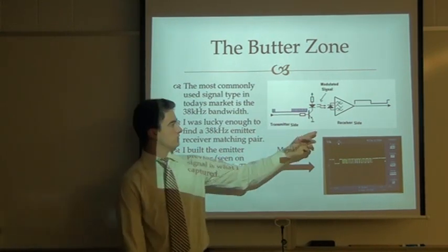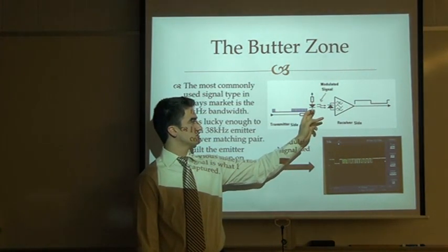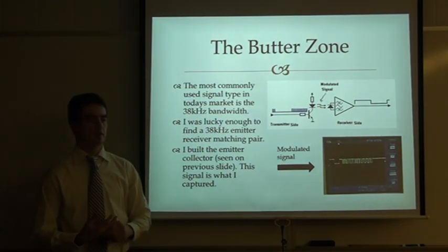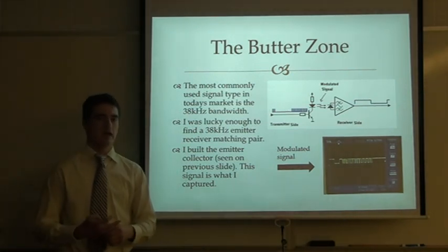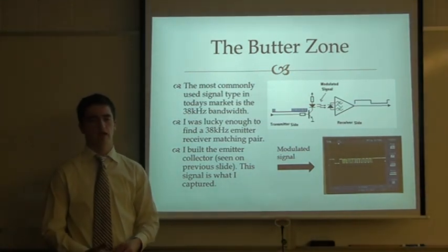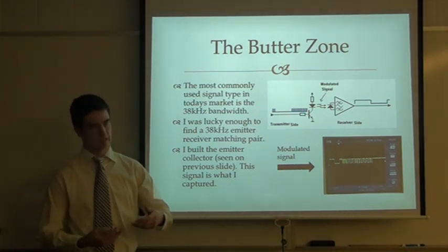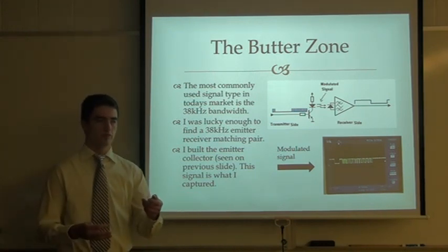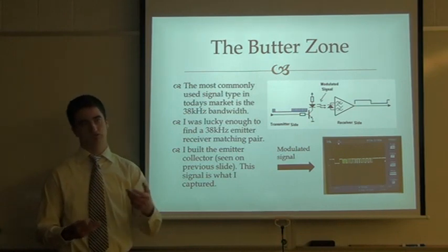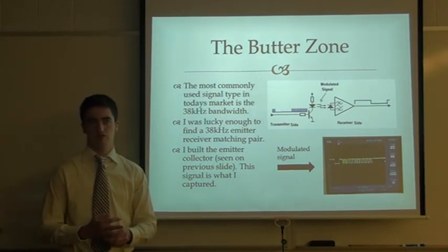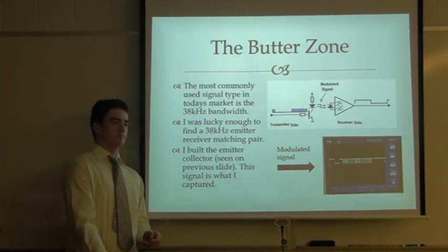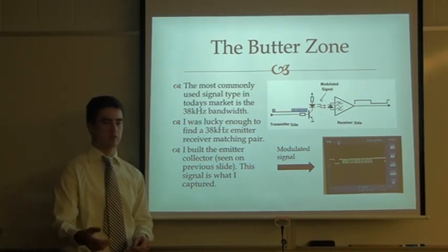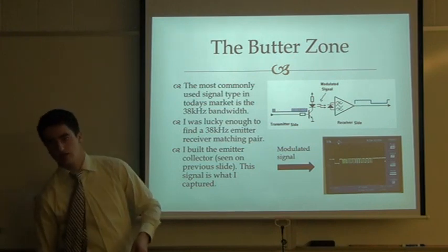So that's why when it goes through the receiving transistor, it will modulate that signal and make it bursts of high and low. And this signal almost resembles a barcode that you would see on anything you buy from a store. Generally it'll repeat the signal, in bursts with repeated signal, in case there's an issue with transmitting. So the receiver will know that for that one burst it received this signal, and it'll essentially ensure that it gets there.